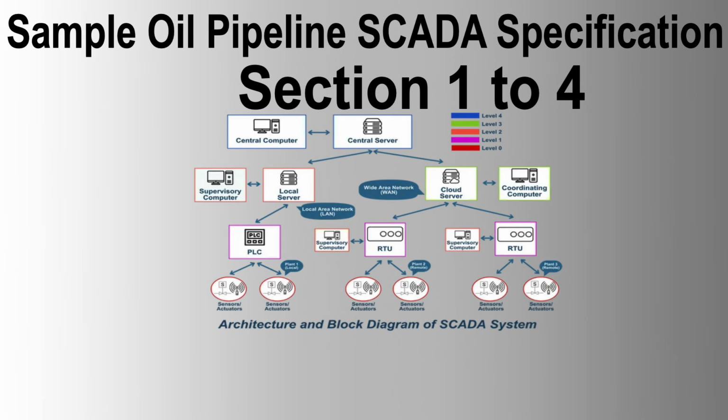Section 9, Communications. Internal communications, fast Ethernet LAN. Networking, dual Ethernet switches and routers, SNMP client utilities. RTU communications, TCP/IP network links with multiple serial communication links. Firewall, dedicated firewall for external connections, protecting against unauthorized access.